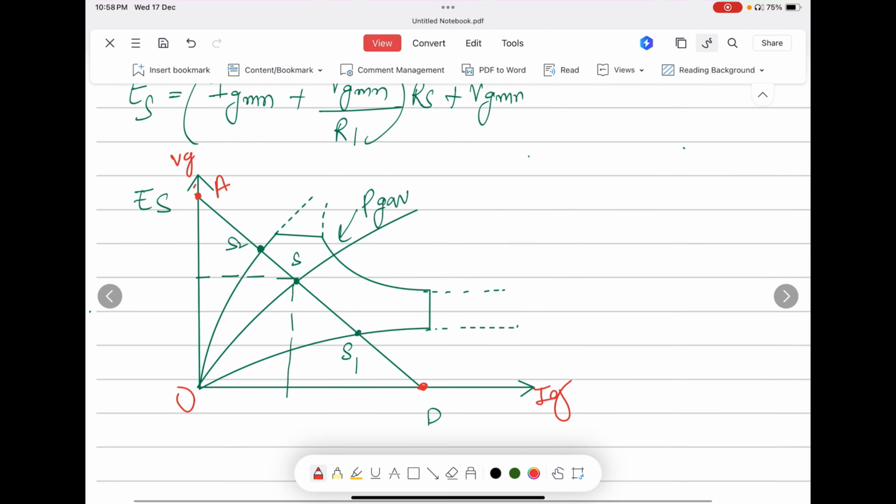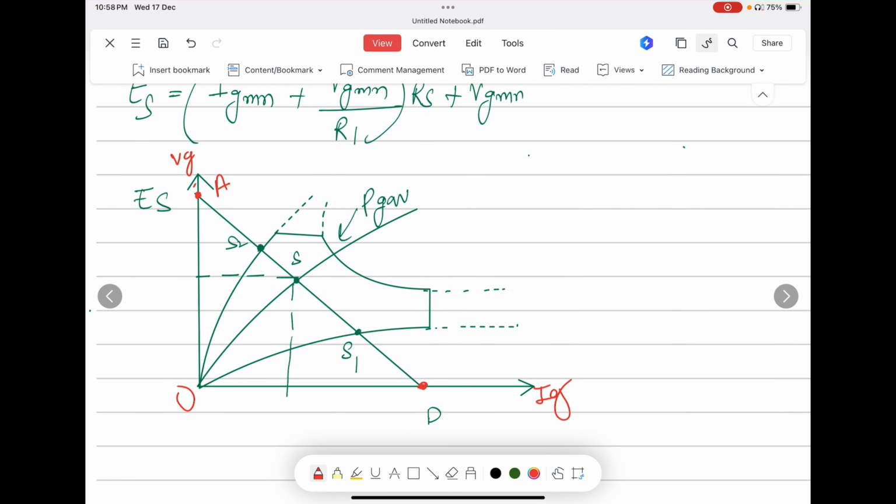So now after we draw this, it intersects at 2 points S1 and S2, and in between these points, this is P average, we have got this point S. It can swing in both ways, that is S1 and S2, but the prescribed limit is this: the thyristor must operate in between this to avoid any kind of damage. Thank you very much.